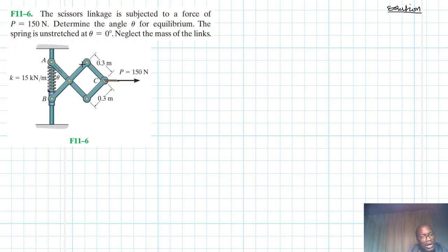So the virtual work method comes in handy. First things first, look at this support here. This support is free to move in the vertical direction. Therefore, we are only going to have a reaction force in this direction, and we denote it like so. We denote this as our Bx. Our A is hinged, or pinned at that point, so it's not able to move in the vertical or horizontal.